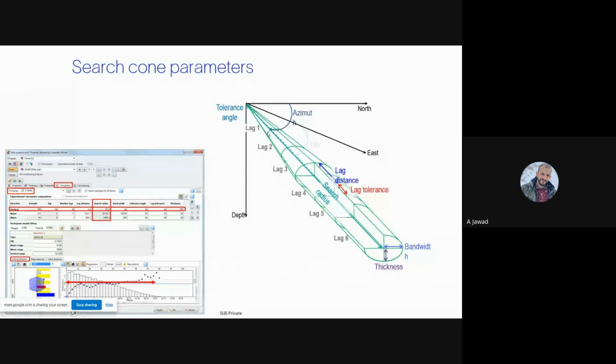So these are the lag distances. Basically, in lag 1, any data that falls inside this distance will be tested for how much variance there is between this one and this one, and then we plug it into the first lag. If you can track my mouse, I'm now moving to the data analysis here. This is the first lag. For the second lag, you also test how much variance there is between the data inside lag 2 and your point, and it will fall here, and so on, until you get variance for all your lag distances. Then you can start matching your model. Until this point, you have finished your job, and the rest is for the software: you need to match the model to your data.